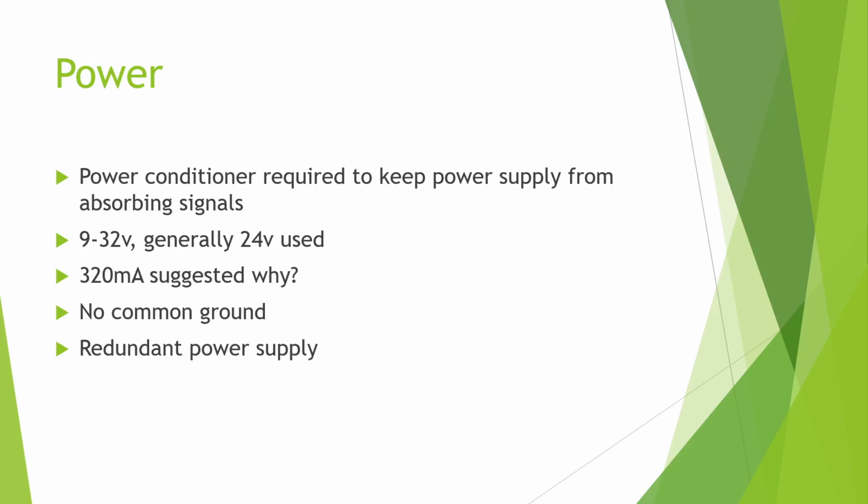Most power supplies are switch mode power supplies nowadays, which means we take the AC in, rectify it to DC, so we have a high voltage DC. We now pulse it at a very high frequency through a transformer. And why do we have to pulse that DC? Well, because we want to go through a transformer. Why do we have to rectify it first if we're going through a transformer? Because the higher the frequency, the smaller the transformer. All right? So we pulse it at a very high frequency through a transformer, which drops that voltage down to a more acceptable level, and then we smooth it and everything out. But that means we have this high frequency pulsing signal happening in this power supply.